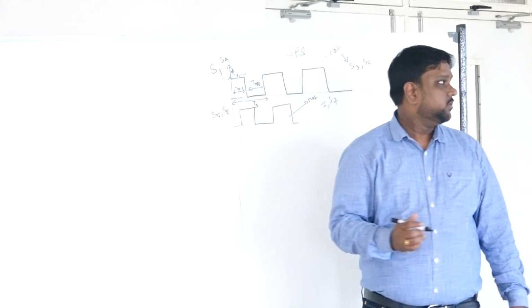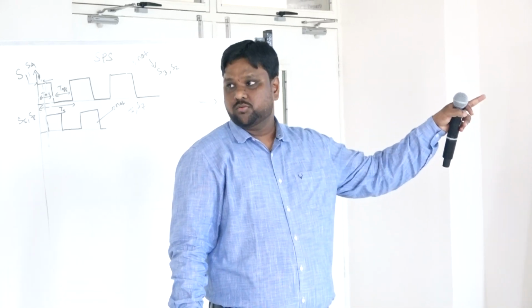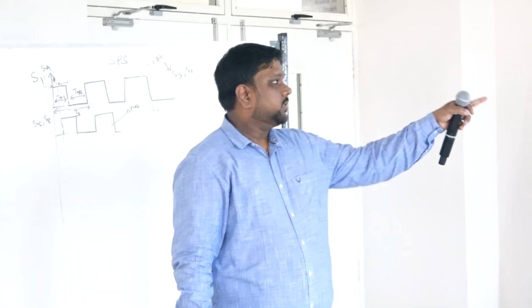Now, how much phase shift? Okay. So that T shift you can give as D into Ts by 2. Okay. That we are going to use in the simulation. It becomes Ts by 12. We can write it as Ts divided by 12. Apply. Okay.